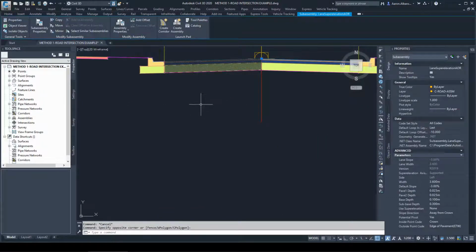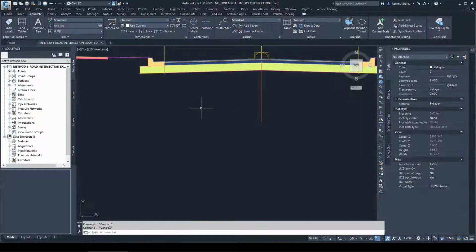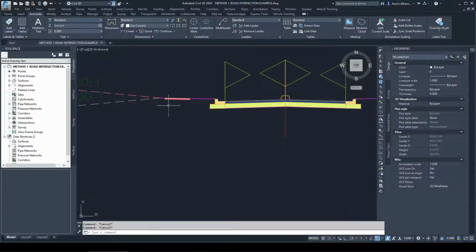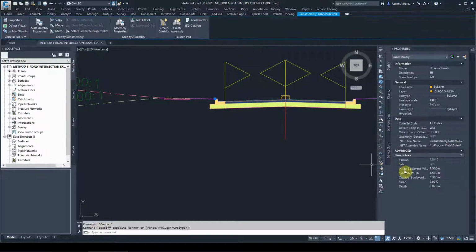That's good to know. Or in other words, I can just select that lane and I'll get all the information: 3.6 meters wide and has a cross fall of -3%. This is the information that we need. I've got a daylight of cut and fill of 10:1 on the surrounding. We've got a side footpath on both sides. We've got an area for vegetation, to grow trees, to place signs, all of that, which is an urban verge, if you'd like to call it, after the curb. And it's called on Civil 3D a pod verge. So this is the inside verge and that's the outside verge, regardless.